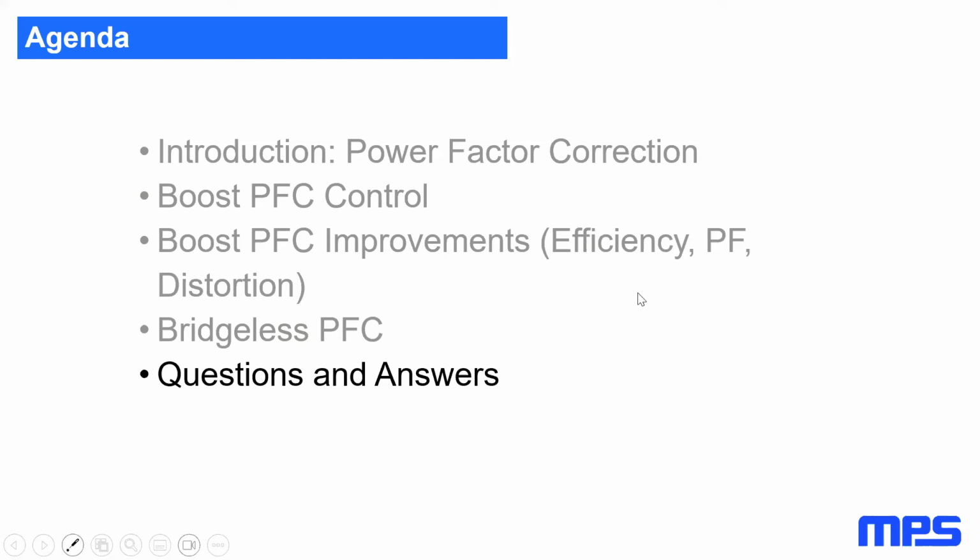Although the individual components tend to be smaller than if you do the equivalent power with a single PFC rather than interleaving, there's still some cost associated to it. But yes, there are definitely improvements on the heat dissipation because you have fewer hot spots, let's say. Also, the totem pole PFC by itself already spreads the power into more ICs or more components, so it's also a little bit better for heat spreading, but yeah, interleaving is better.